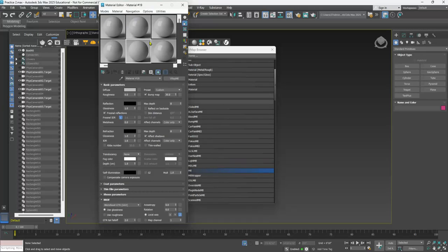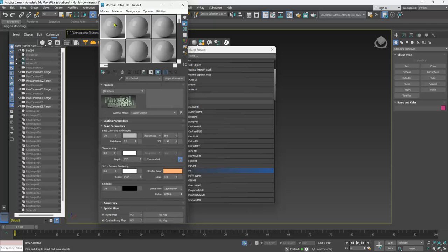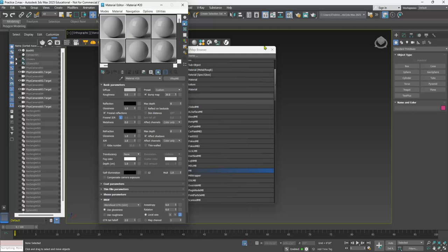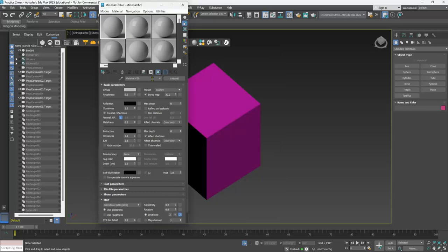Oops, sorry, because I had this one clicked. Let me go over here. I'm going to pick the top left again, select the material V-Ray MTL, and there it is. Now I can close this. Once the material is here, what should be the first thing I do to the material? The first modification, to be really organized. Think of it as layers. Name, yes. Always give it a name. So on top here, I'm going to call this concrete.